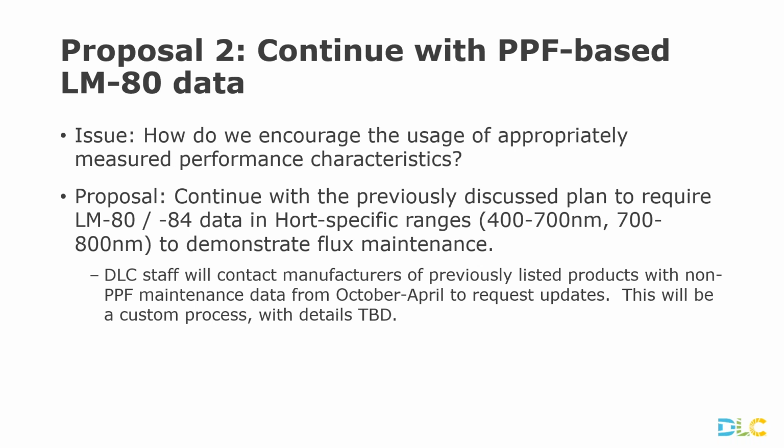So what we've been doing for the last year is we are accepting qualification of products with LM80 data that's in radiometric watts or in lumens-based terms, i.e. non-photosynthetic photon flux. However, at the start of the program, we said, we have a year to do this. If you do not have PPF-based LM80 data, then we are going to stop accepting it in new product applications starting on October 15th.